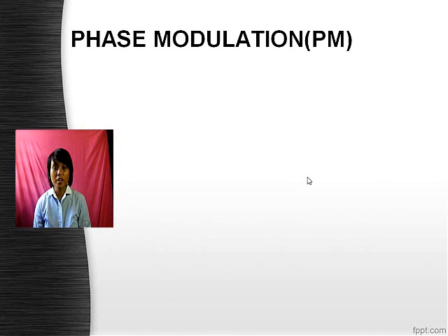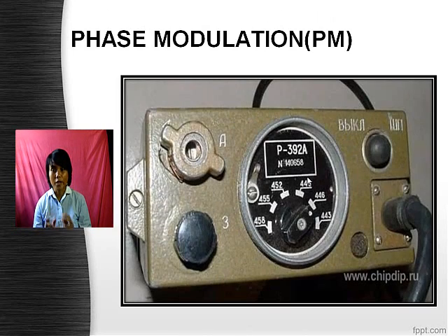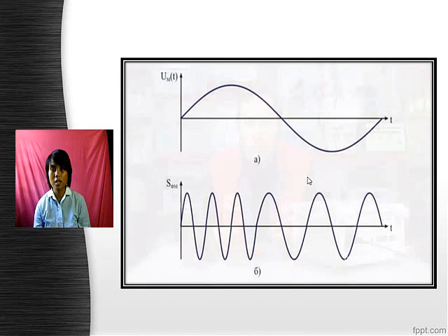Frequency and phase modulation have become widely spread in the VHF range. One of the advantages of phase modulation is that it is easy to use. For example, VHF direct conversion radio stations which use phase modulation are among the simplest ones, but still remain as effective as the radio stations that use single side band modulation. In addition, phase modulation has other advantages. Thus, the power of a transmitter does not change during the modulation. It remains constant and equal to the peak value.